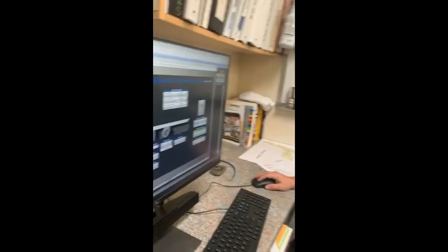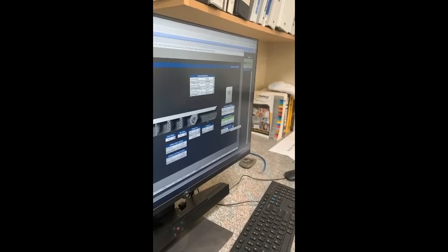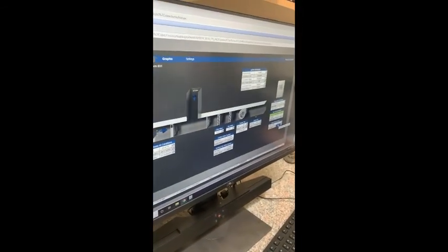The filter is just a maintenance reminder, so there's nothing that actually monitors the differential pressure across the filter. You have your occupied heating and cooling set points and your unoccupied heating and cooling set points, and then you can see here the set point offset. If we went over there and the user turned it up, you'd see this set point offset change. If they put the fan into auto or off, speed 1, 2, or 3, it would show here.